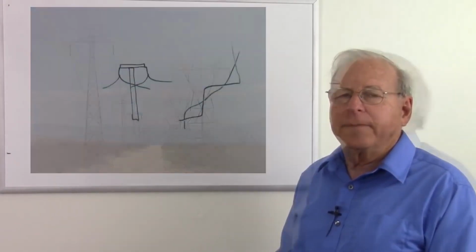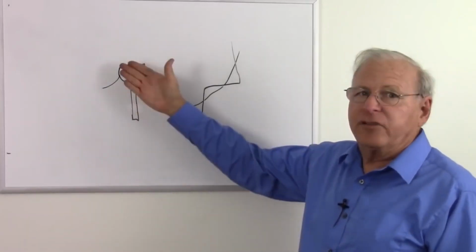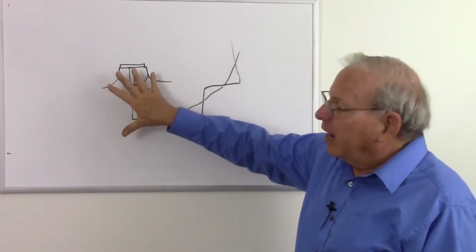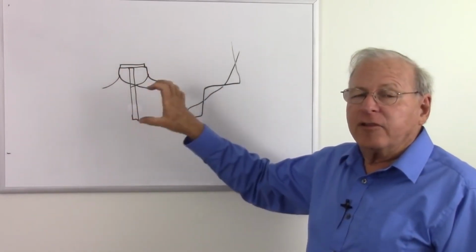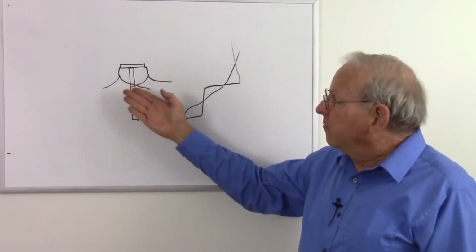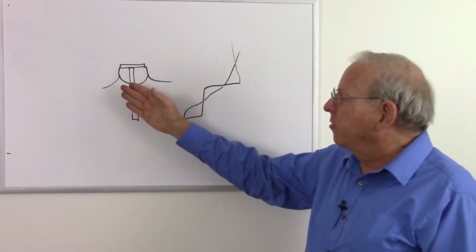And the cost of the rectifiers and the inverters needed to convert to DC and back to AC is coming down to the point where you might see these DC lines becoming much more common than they are now. The actual building of the line is cheaper. There's less wires. You don't have to carry 3 wires with the infrastructure to carry 3 wires.